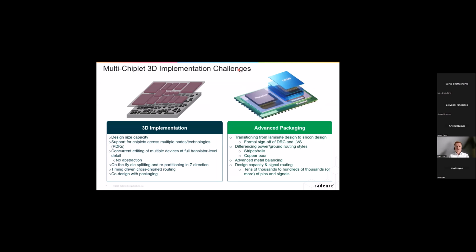And even more complex is the real 3D implementation. So in this case, you design or disaggregate one big RTL netlist into two different fabrics. So you may want to do floor planning, moving the functions or the blocks in Z direction from the top die to the bottom die.